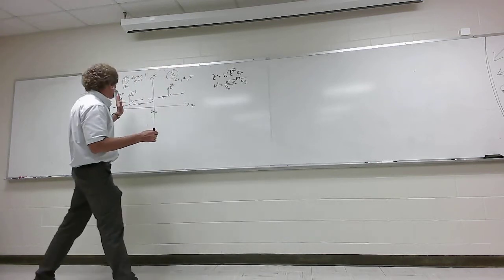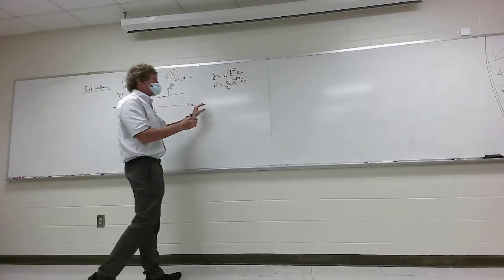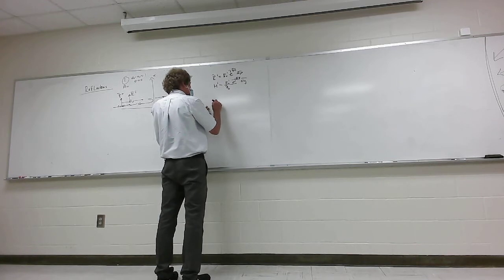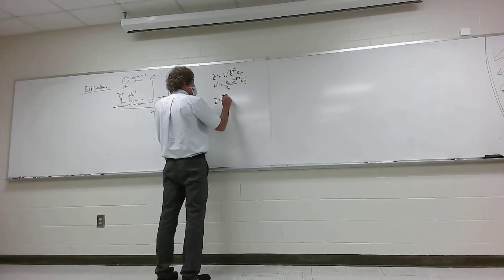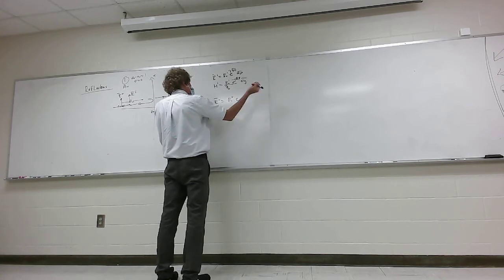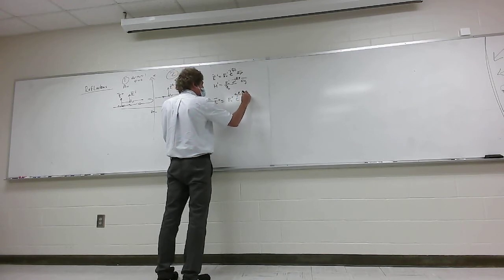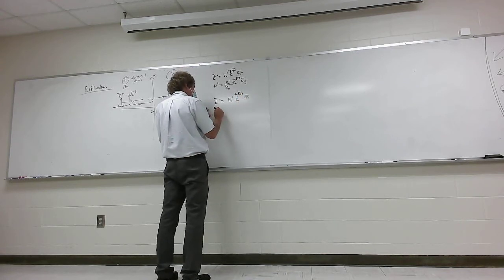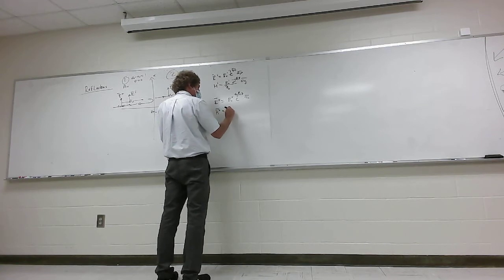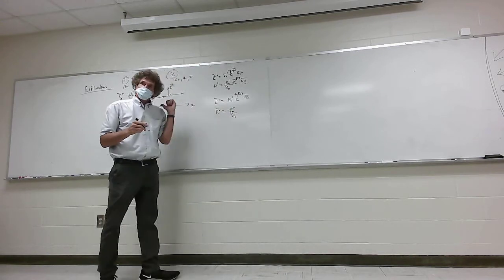That's the wave coming this way. Now the wave reflected will be equal to some E naught reflected, e, but it's going the other way, so it'll be plus j beta 1 z in the ax direction. And H reflected will be equal to E naught reflected over eta naught, but it's going to be minus because it's going the other direction.